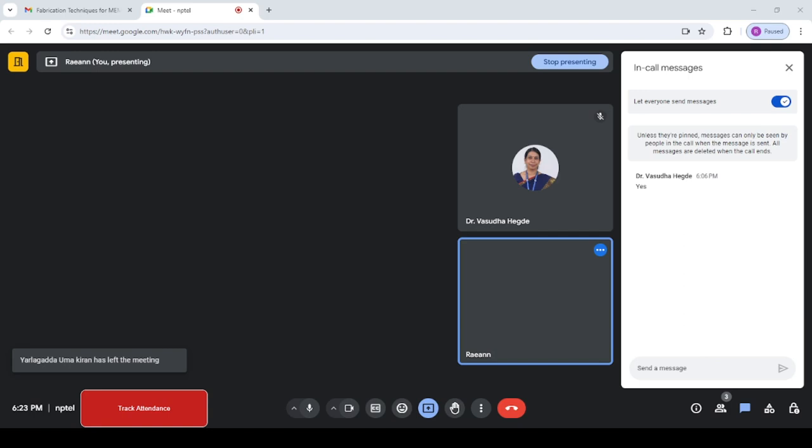Another important thing is, when we want a metal to be deposited, we don't want any reaction to happen on the substrate. Our substrate should not react with whatever ambient is present inside and form some other film. So whatever gas we use also has to be inert. Argon is an inert gas. It does not react with the target, though it bombards the target. It should not react with the target to form some other film on the surface. It can also be used as a carrier gas for other gases required in the process. So the answer is all of these, option D.